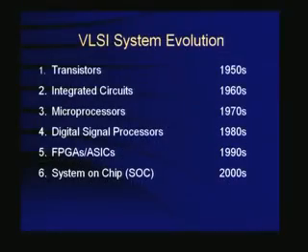And then digital signal processors became a new family of device processors. The difference between microprocessors and digital signal processors is that digital signal processors have some specific functions that can be performed with them, which are not possible using microprocessors. Like there is a hardware multiplier. A microprocessor may not have a multiplier. Even if you have a multiply instruction, it is performed by some sort of a microprogram, whereas a digital signal processor has a hardware multiplier, and has other features like Harvard architecture and all that.